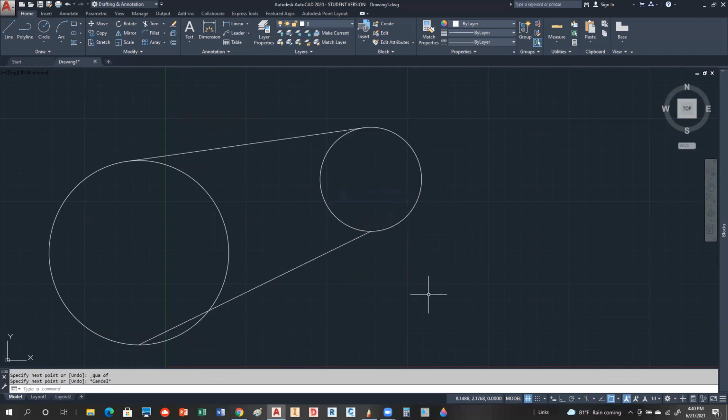Okay, so you can clearly see that this is tangent. This line's tangent to those circles because it's only touching that circle in one spot. But quadrant's not the same thing at all. What quadrant is doing is giving me a line that's coming through here twice. So that's actually what you would call a secant line. The reason I wanted to show you that is because tangent is not the same thing in any way, shape, or form as a secant, okay? So I'm going to go ahead and just delete this guy.